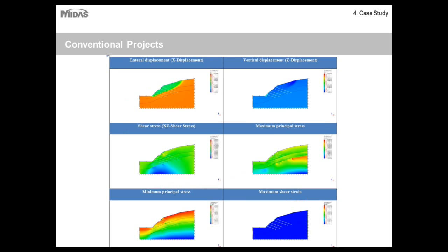And then last, just a very straightforward slope stability project. As you can see, I modeled this project with a limit equilibrium method as well to get the factor of safety, but because it had certain soil nail reinforcements, also known as tiebacks, involved, I decided to run a strength reduction method just so I could check the shear stress. As you can see, the stress pattern changes because of the presence of these tiebacks.